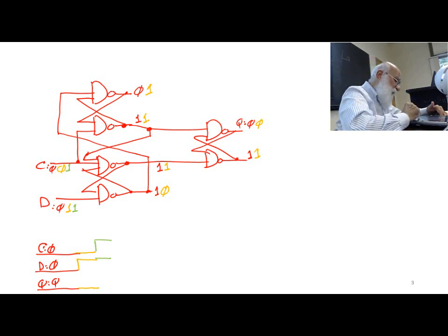Actually, there is this, and that changes the gate right in front of it, and therefore the 1 there, there is a 1 up there, there is a 0 up there, this doesn't change, that remains 1. Then there is this 1 going into the gate, the second gate from the top, which is this one, and then there's another 1 there, and that changes the output of this gate to 0.